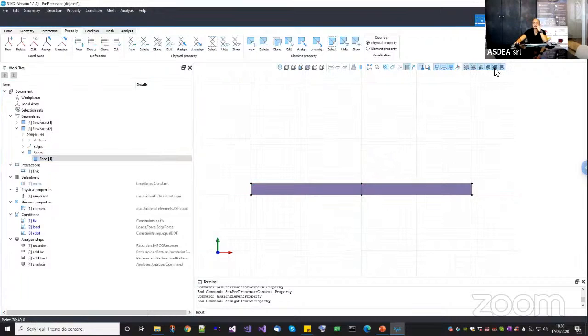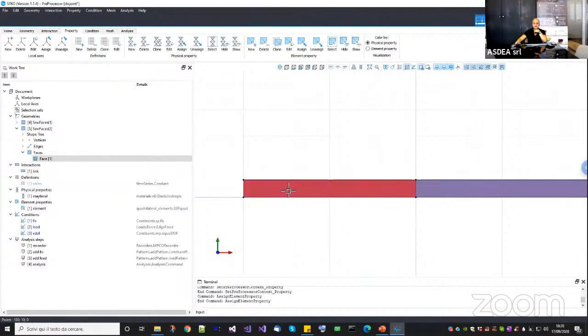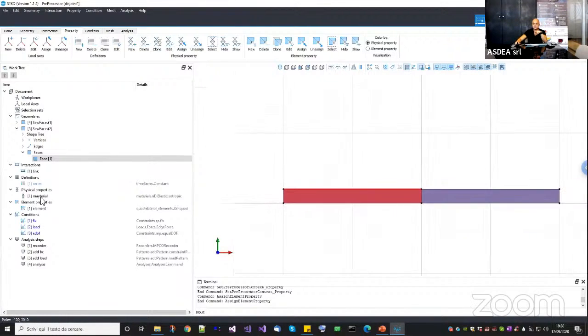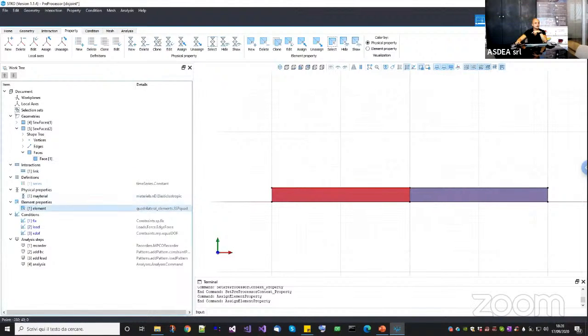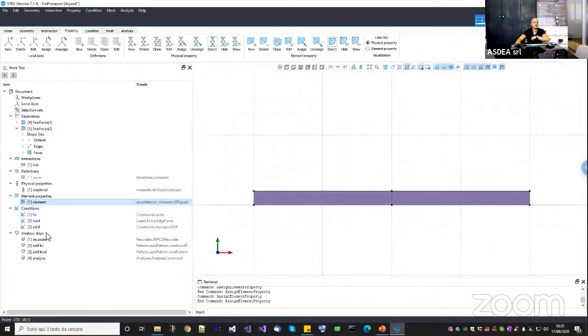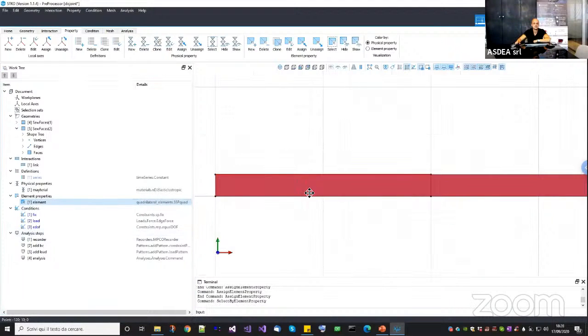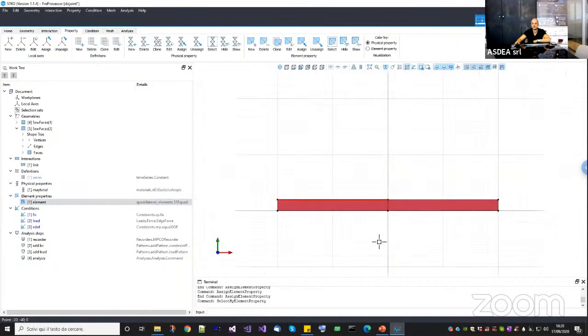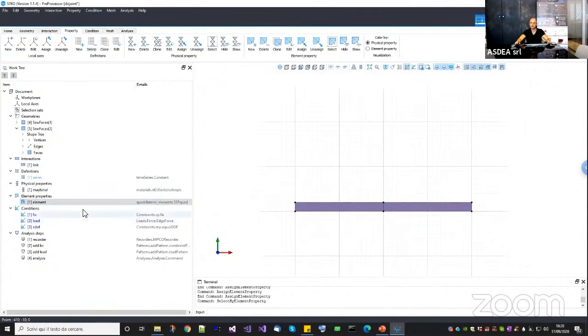But if for some reason I'm not in the full selection geometry, but I'm in the sub-selection, and I select this face, and also by mistake, I select this edge here. Now, as you can see, I also have the edge selected, and I drag and drop the element property. And if I try to select them, I do select, and you can see that I have selected one face, two faces, and the third edge here. This one will give me an error.